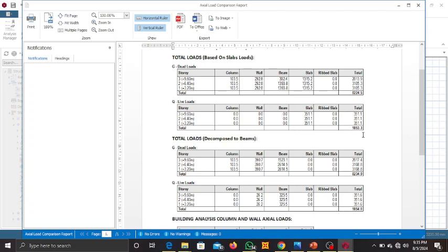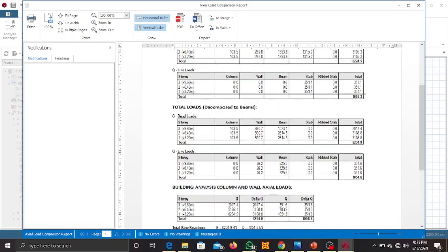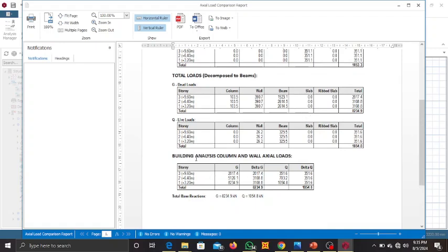It's not making the building stable. You have to go back, check your model again, redesign and reload your structures, and if possible look for a way to avoid sway and all of that. So that's how you know that your building analysis is correct: at most 5% discrepancy from all of this. So you check your building analysis column and what Excel gives, which is 8,234.91.